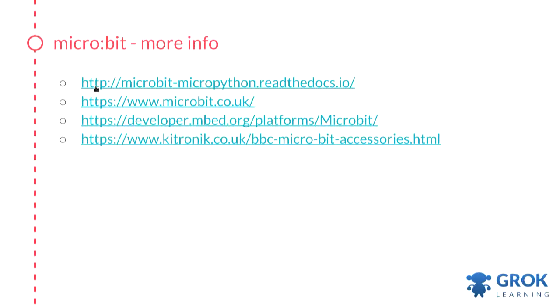So some more info, the MicroPython documentation, the MicroBit website itself. The third link is interesting. The MicroBit is an ARM-based development platform. If you have really advanced students who actually want to break free of the provided sandbox and treat this as a professional thing that a real software engineer or a real hardware engineer would work on, you can download all the ARM-based tools that use the mbed platform and build C++ code from scratch. This is a board that actually is quite limitless in terms of your options and things to learn from it. And then Kitronic are one of the providers of accessories and so forth for the MicroBit.